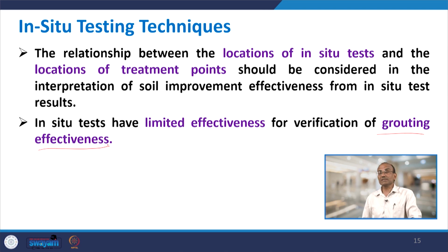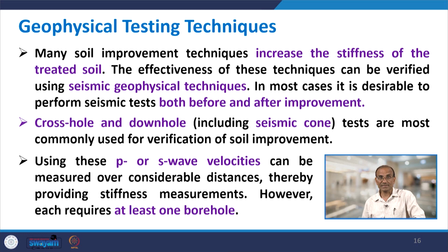So, there are 2 points to check: one is the time which has elapsed after the improvement, and the second is the distance, that is the location of your testing site with respect to the point where the improvement has been done. These need to be considered while we use the in situ testing technique.